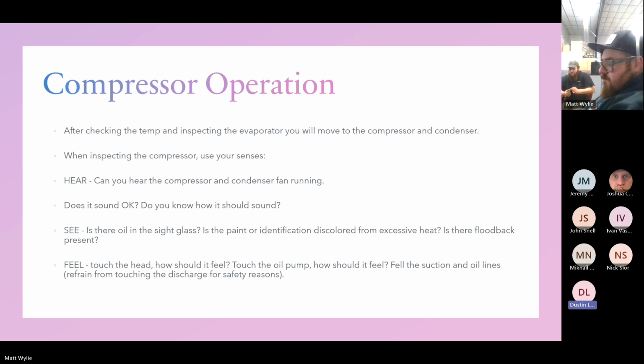But verifying that you have 0 volts on your meter from top to bottom across any disconnect, contactor, or switch, you know that your switch contacts are good. So when we're doing PMs, don't just check that you've got 208 coming in. You should be 0, top to bottom. Just in case no one's ever checked that.